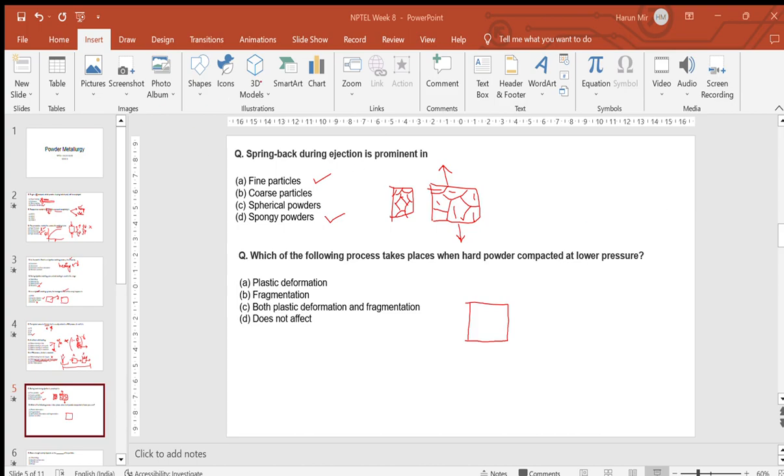The second says it is an insufficient binder quantity, so all the voids between the particles cannot be filled. The third option is excess binder quantity and separation of the powder and the binder. Four is excess binder quantity to coat the particles with binder, to break the agglomeration and to attain uniform distribution of binder and particle size. So which of the options is right at mixing of 85 volume percent of binder?